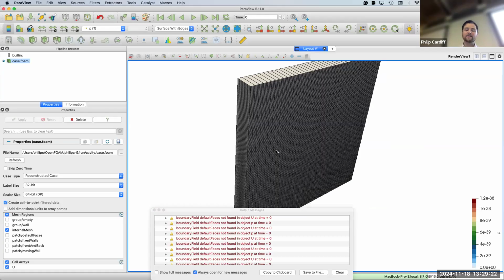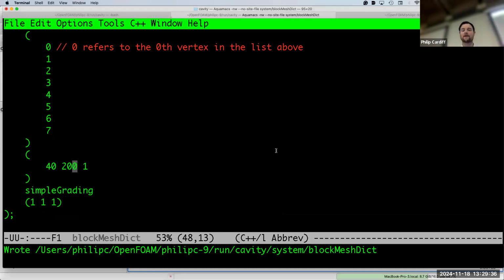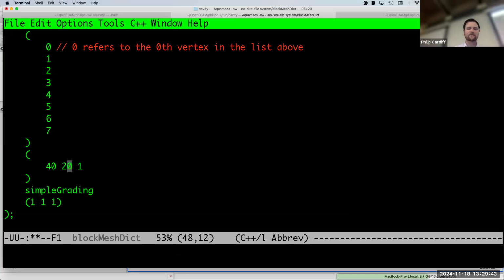Okay, so this is a very simple mesh, but blockMesh can be used to create complex geometry. Some things, for example, like turbos or pumps can be described by simple geometry, like with curves. And if you have a mesh set up with blockMesh, it's very easy because it's parameterized. You can very easily and very quickly generate a new mesh. So if it is possible to use something as simple as blockMesh, it makes your life much easier. Okay, so let's step back to 20.